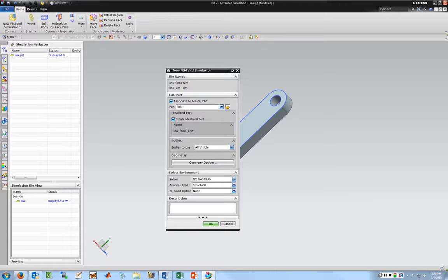You might if you need a different solver. This is just going to use Nastran. You can see the other options here. There's quite a few. A lot of these depend on what licenses you have. Nastran, it's a pretty good one to start with. You can see something about thermal and flow. I don't know exactly what flow it does. Really, this isn't CFD, so you need a completely different application, something like ANSYS Workbench to do CFD. But there's some options here.